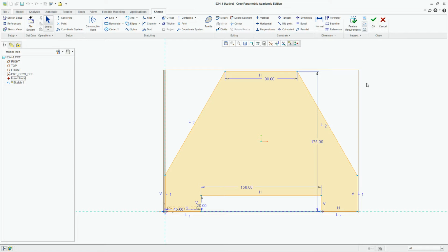One thing that you do want to check before you finish any sketch is it should always be shaded. So the check for you to do is, is it shaded, yes or no? Obviously your answer needs to be yes. Are there any weak dimensions? If you have a weak dimension, that means you're missing a dimension somewhere else, so make sure all your dimensions are strong. If you see a red dot somewhere, for example, if I delete that line, I get 2 red dots. Those red dots indicate that I have open-ended geometry. You want to make sure that you have no red dots either. Everything needs to be closed, clean, and precise to make the 3D models.